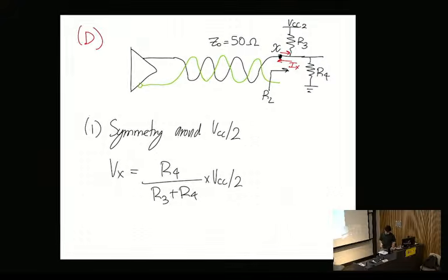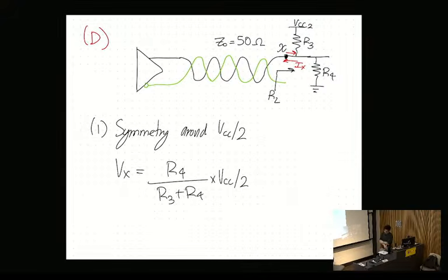Now let's consider with the currents. So what would the value of current be? So again, let's just use superposition, right? Anytime we have multiple voltages and multiple currents, we have a contribution. So this we can think of as almost like the DC offset. Now we have a current being either injected into the node or being taken out.